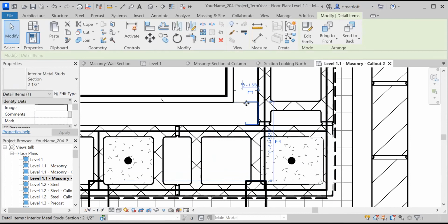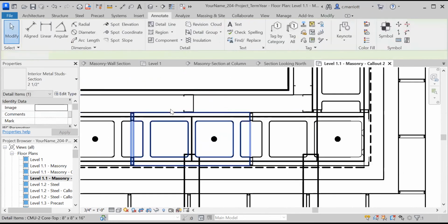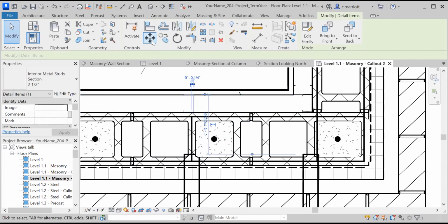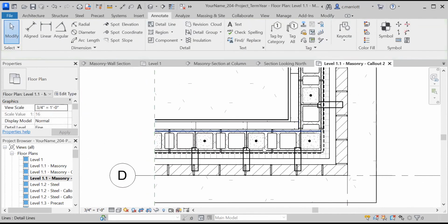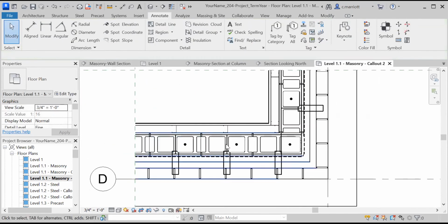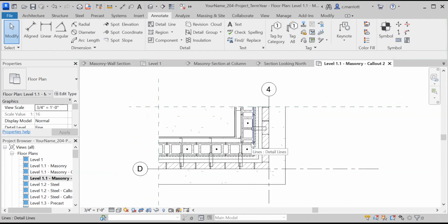And we'll need an extra one, maybe sometimes they double them up, but I will just go ahead and draw 16 inches. Some of the details you kind of leave to the carpenter to resolve. If it's important, you're going to heavily dimension and notate it. All right, that should do it for the detail components of this plan detail.